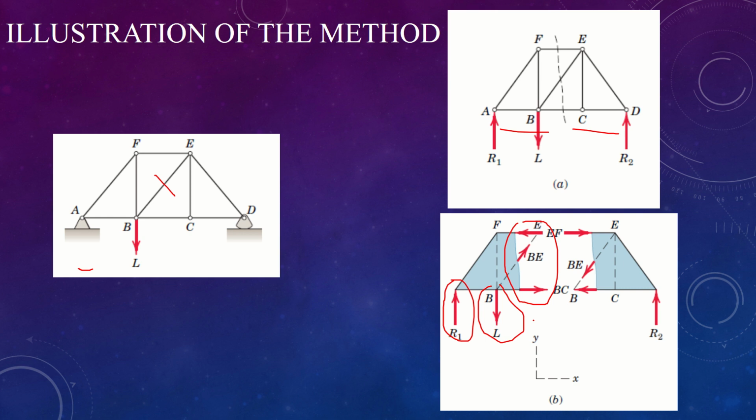The equation of moment about joint B eliminates three forces from the relation, and EF can be determined directly. The force BE is calculated from the equilibrium equation for the y direction. Finally, we determine BC by balancing moments about point E. In this way, each of the three unknowns has been determined independently of the two.